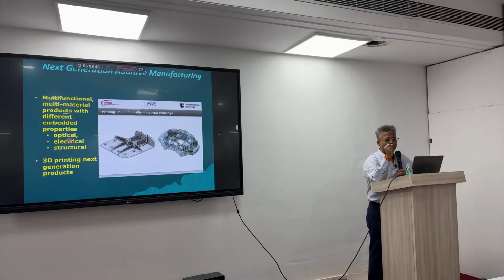If there is any damage to the component, or something is going to happen to that component while it is under process, under action or under service, then the signal will change. As you know, if a crack is going to form, the vibration characteristics will change. So you get different kinds of signal patterns. Before the catastrophic failure takes place, you will be able to diagnose in advance that there is likely to be a failure soon.